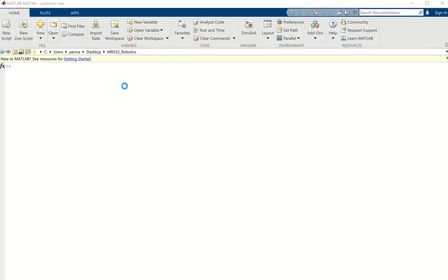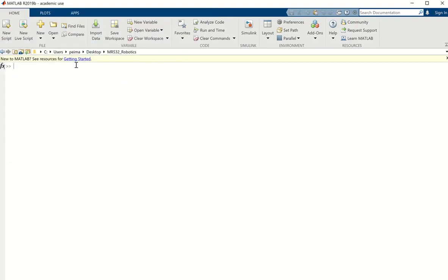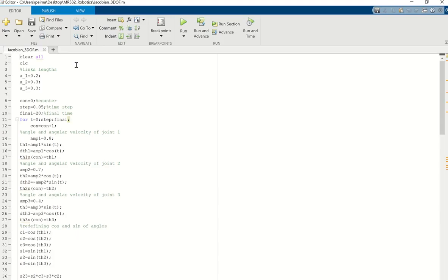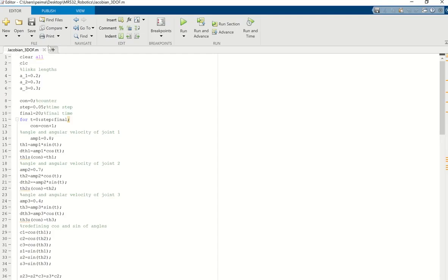So here we go. At the top of your codes, as I taught you previously, always say clear all and clc. clc clears the command window. Remember, like here, I say A is equal to 2. Now I say clc, which means clear, everything gone. And clear all is going to clear the parameters that you ran in your workspace.